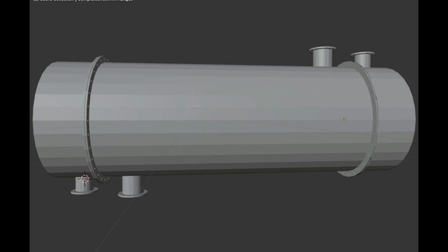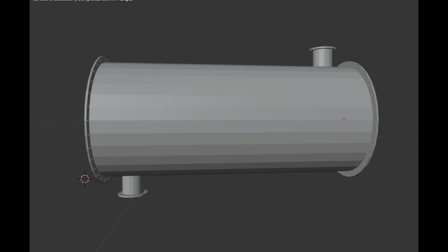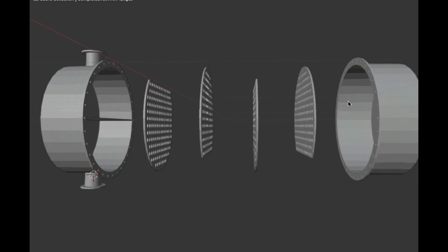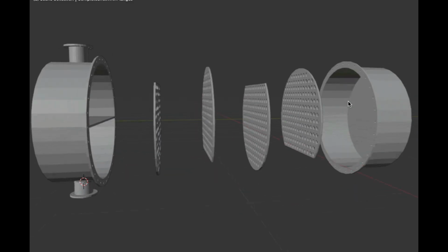However, heat transfer takes time, and we might need to make the heat exchanger very long to fulfill our requirements. To make the heat exchanger shorter, so that it, for example, fits better where we want to place it and to make it easier to handle, we can let the tube side have two or more passages. Here is an example with two passages. Both the inflow and the outflow are now connected on the same side of the equipment.